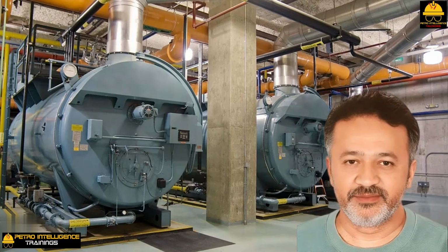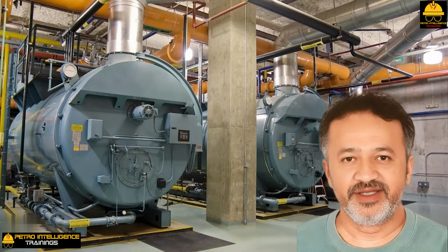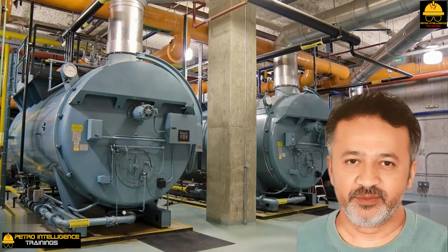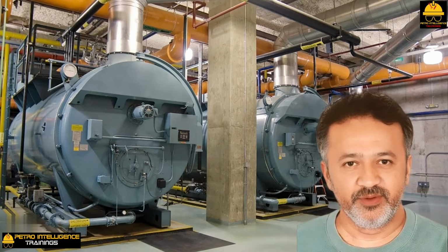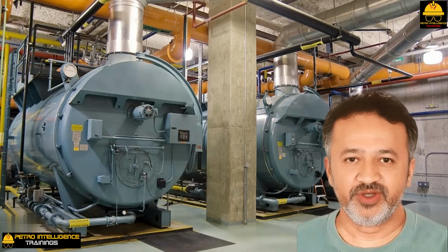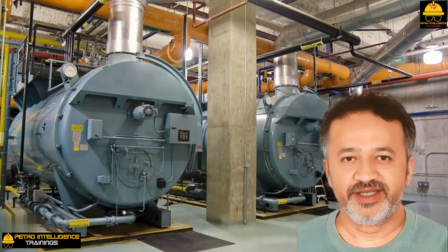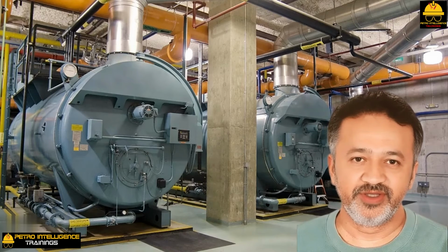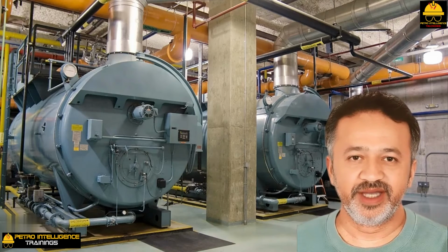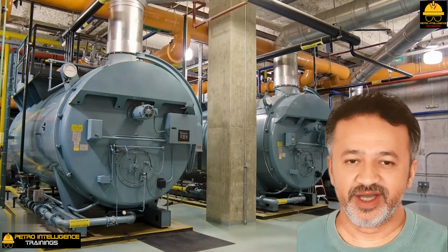Condensate polishing. The recovered steam condensate may often be contaminated with oil. As the condensate will flow into the lower portion of the deaerator, this possible oil contamination must be removed to protect the boiler tubes from the formation of non-wettable films on the heat transfer surfaces, which interfere with the detachment of bubbles, so that the boiler tube surface is then not sufficiently cooled by boiler water, thus causing severe corrosion and tube failure.